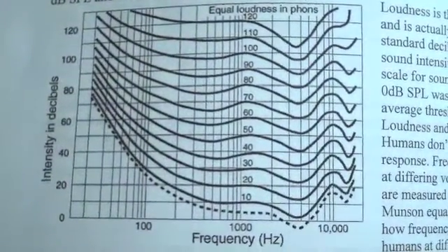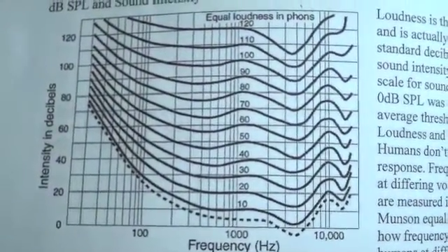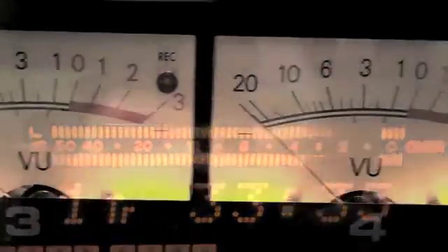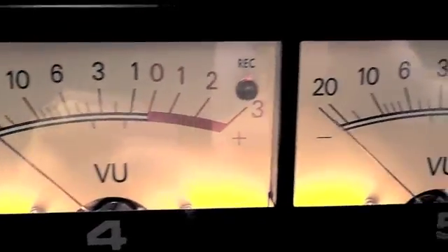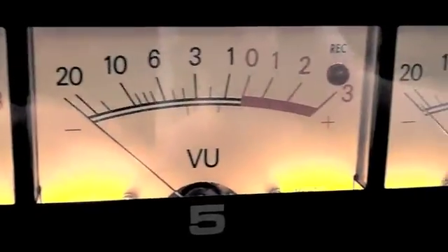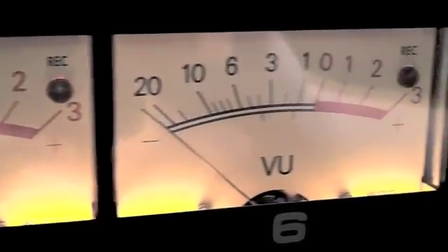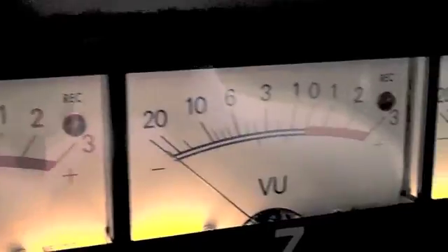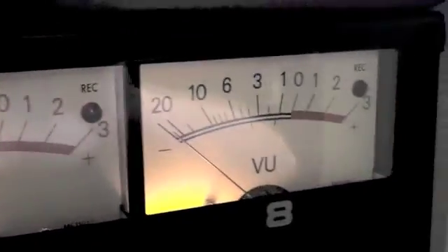Acoustic volume is measured according to the dBSPL scale. Professional audio signal is measured according to the dBu scale. Consumer audio signal is measured according to the dBV scale. Digital audio is measured according to the dBFS scale. The dBVU scale on electronics is set according to the standardized reference level of the device's application. The reference standard may also be referred to as nominal line level or unity gain. Unity gain is typically set to 0 dBVU.